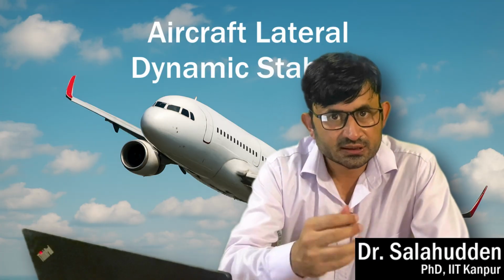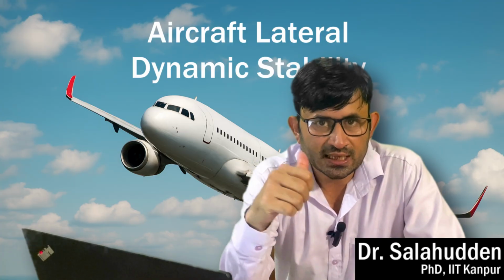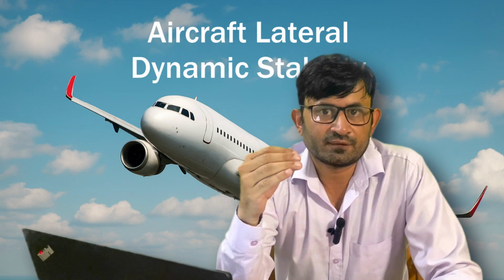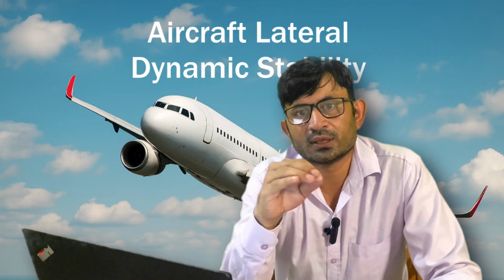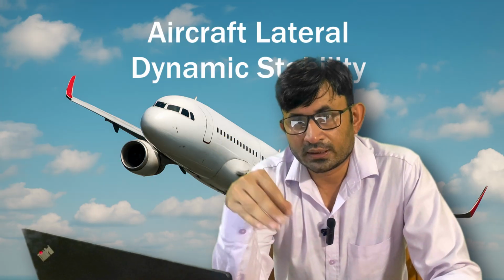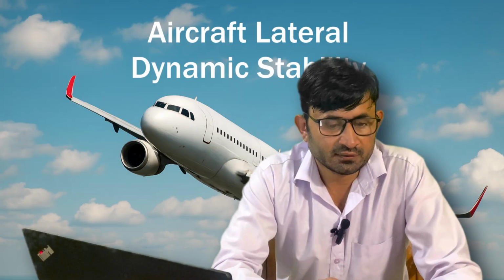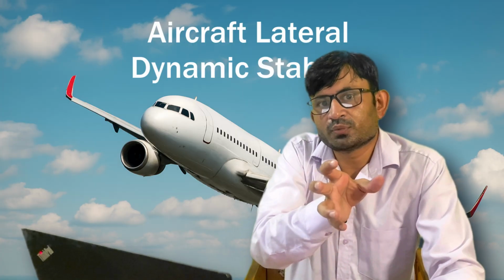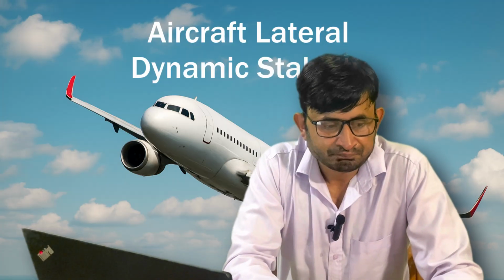So in this lecture we will continue from the previous lecture. In the last lecture I explained to you about the aircraft lateral dynamic stability. We found the damping derivative due to roll rate, and we tried to correlate it with the CMQ which we found in the longitudinal case.